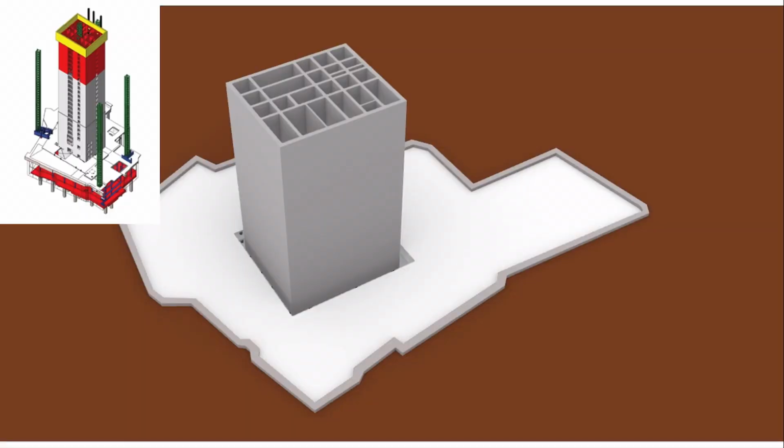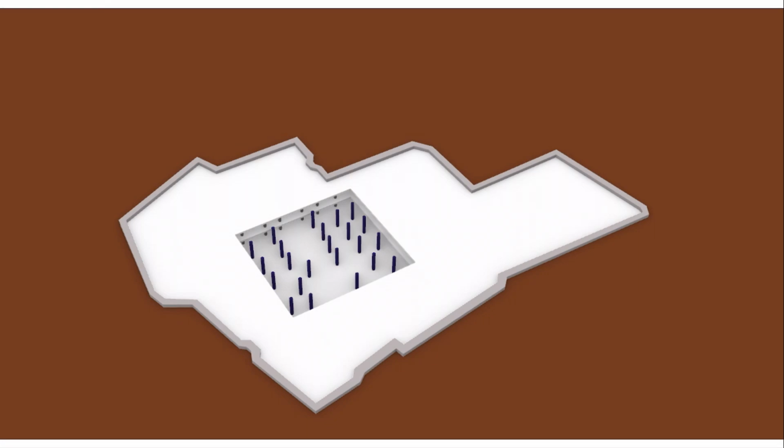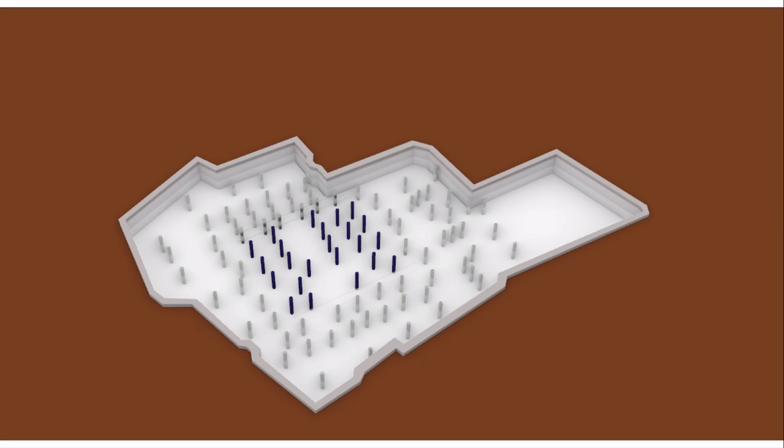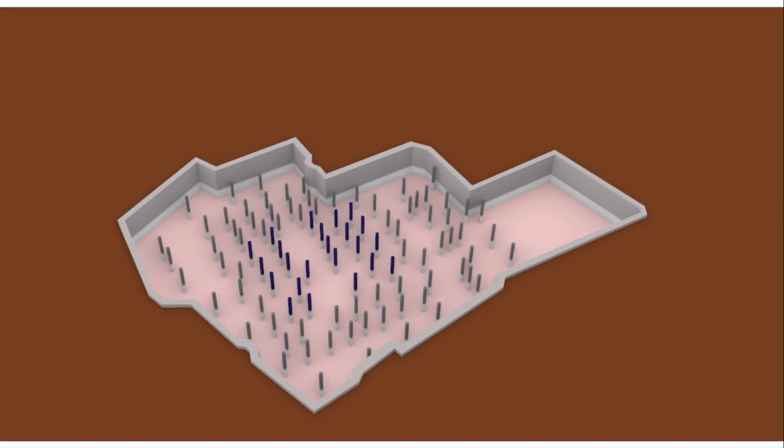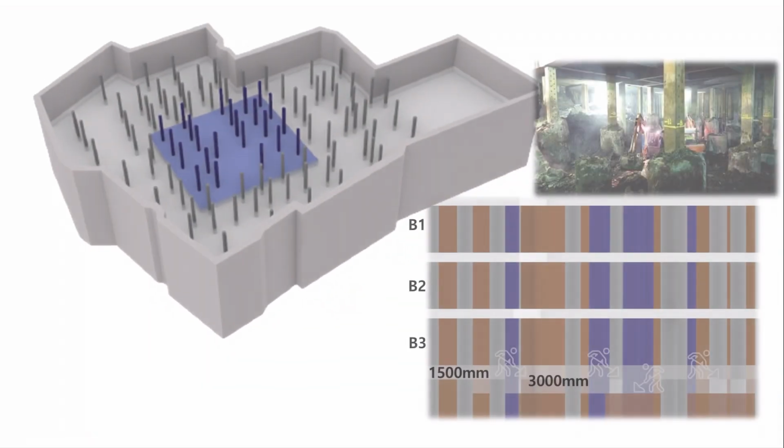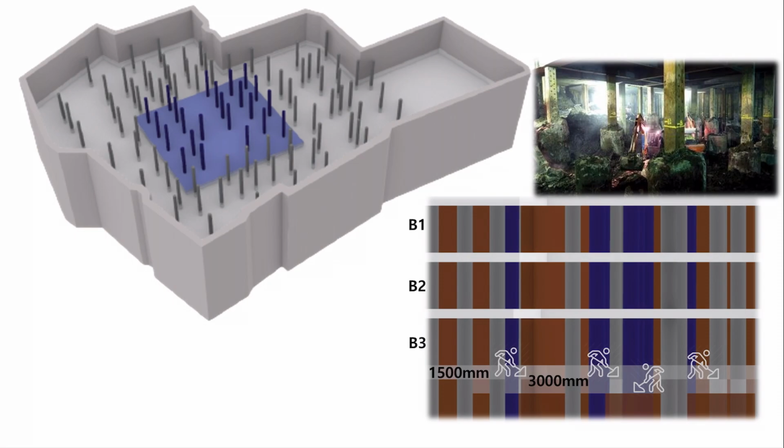This is the 4-step process in top-down construction. It's poured to the second basement floor and supports the core with a slab on the second basement floor. And on the third basement floor, we are installing a raft. Just below the core, which is expected to have a lot of load on the raft, the thickness was planned to be 3 meters and the rest 1.5 meters.